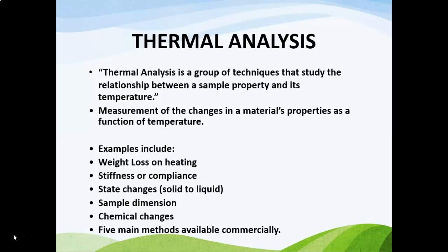All thermal analysis instruments have features in common, that is, a programmable temperature controller, an analysis module, and output devices. Examples of what you can measure include weight loss on heating, stiffness or compliance, state changes, for example from solid to liquid, sample dimension, and chemical changes.